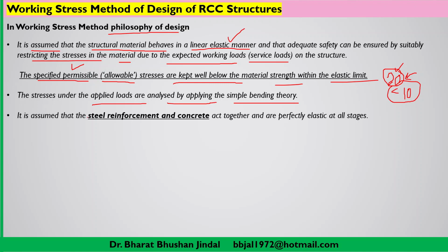It is also assumed here that steel reinforcement and concrete both act together and are perfectly elastic at all stages. This assumption means that steel and concrete act as a composite material and behave as perfectly elastic. This is the assumption in the working stress method.